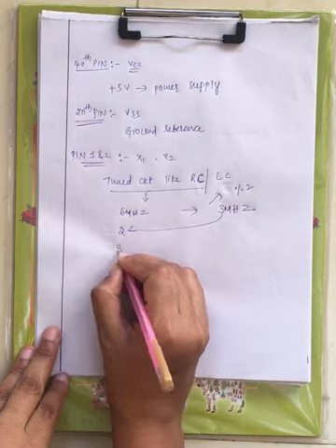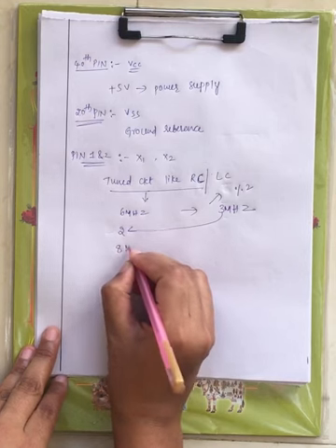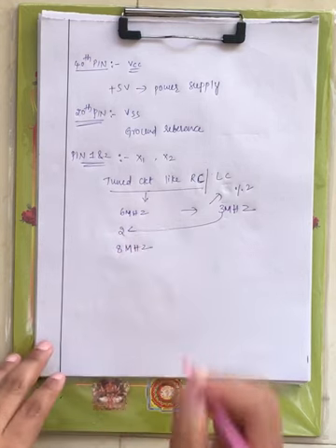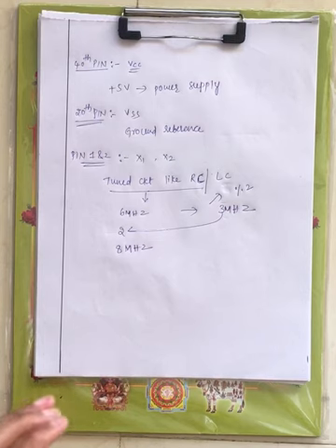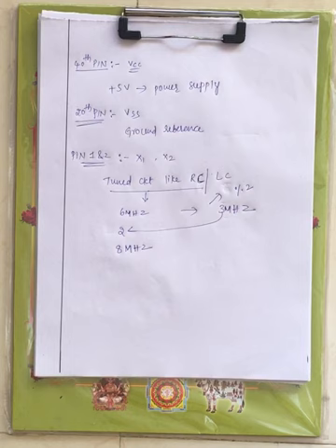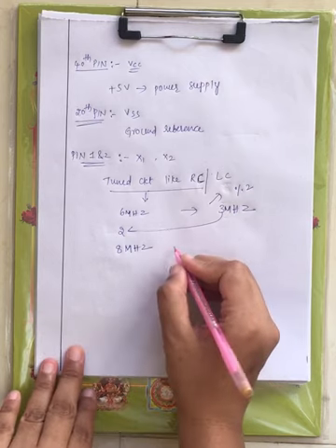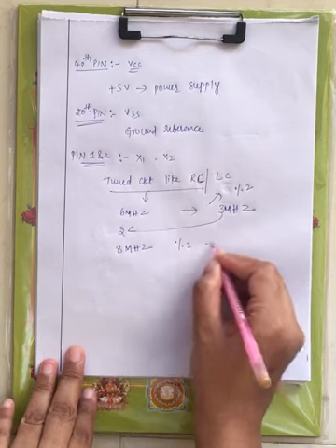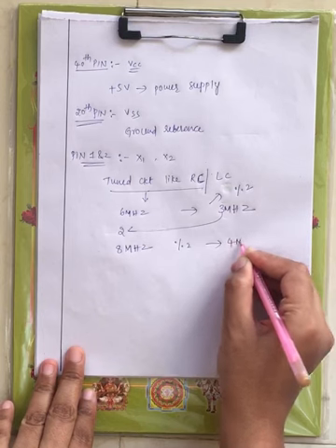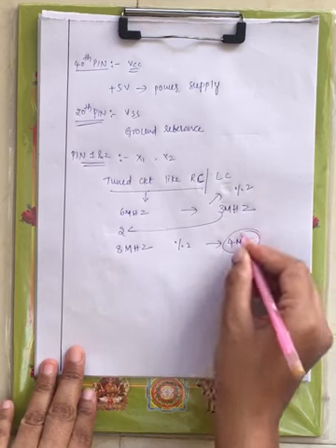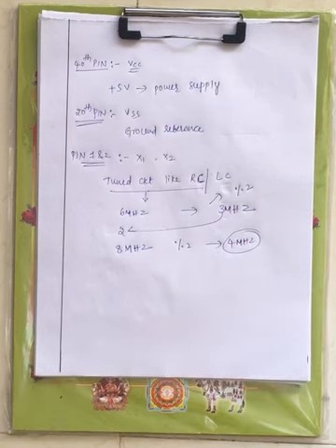Now if you are providing the oscillator frequency as 8 megahertz, that means the tuned circuit that you have connected at pin 1 and 2 is providing a frequency of 8 megahertz. This oscillator frequency divided by 2 will give you 4 megahertz. At this frequency the processor will operate. We have to make sure that we provide 2 times the required frequency.